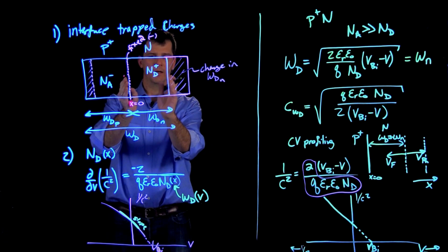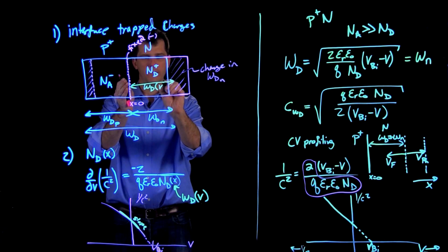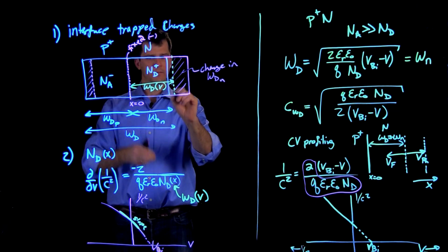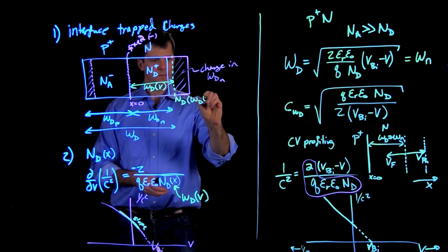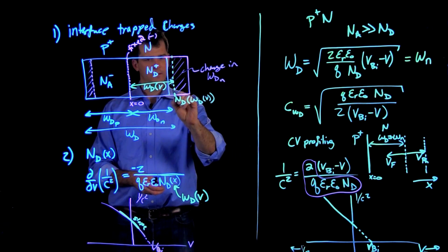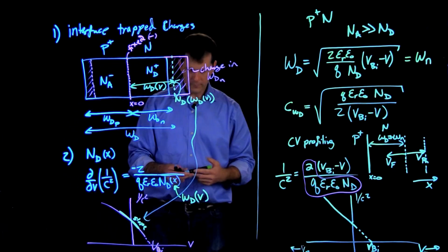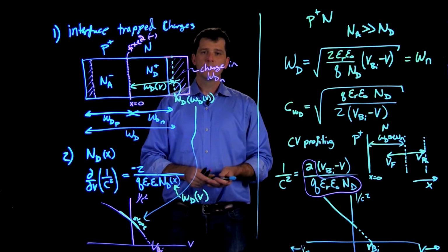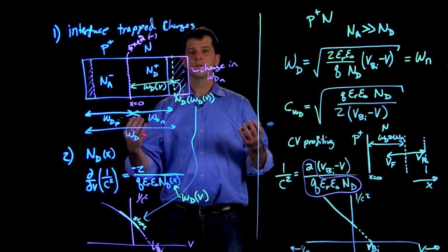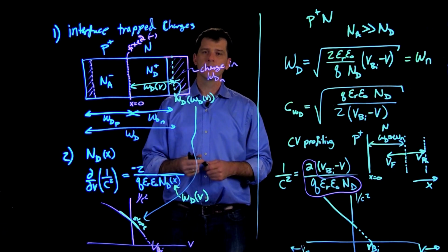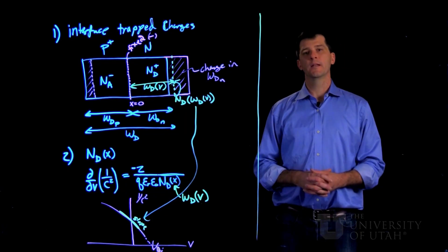We apply some reverse bias, and our instantaneous depletion width at some applied voltage is here. We're actually measuring N_D of this depletion width at that applied voltage from the local slope at that point. So this can be used to profile through non-uniform dopant densities, especially those produced by diffusion or ion implantation into the semiconductor. So that concludes our discussion of the pure electrostatics of p-n junctions.